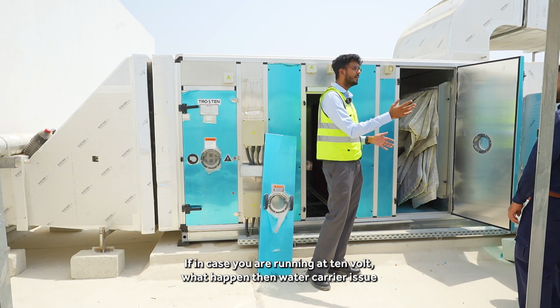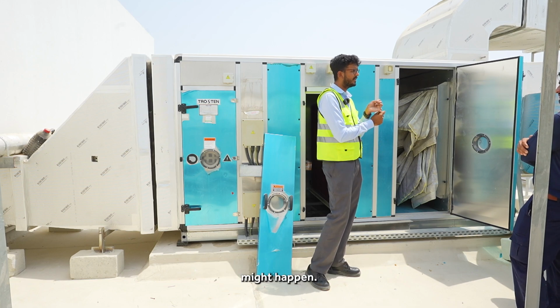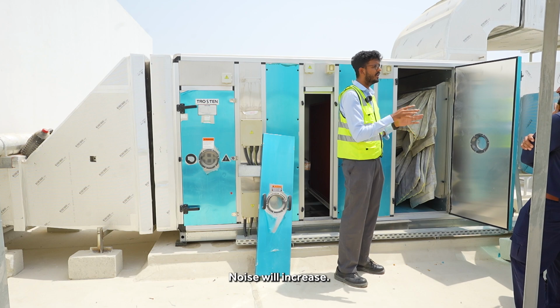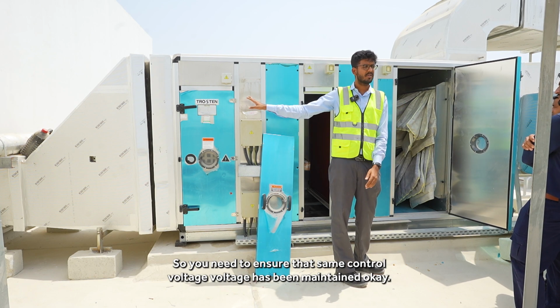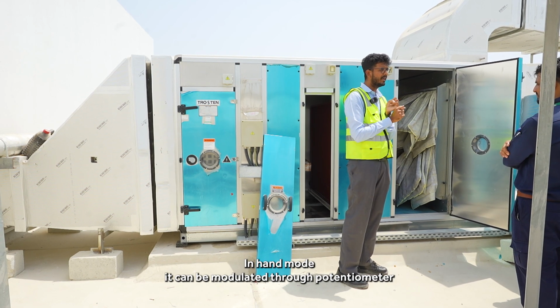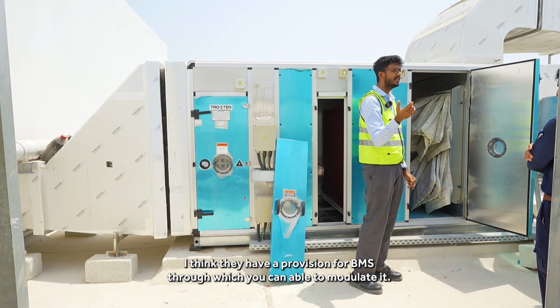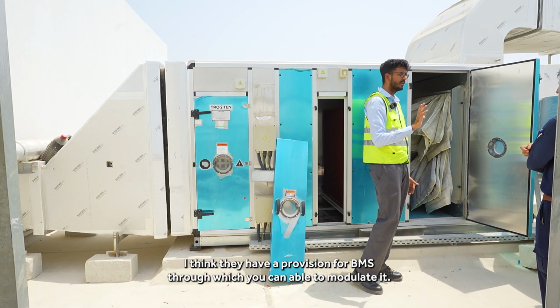If in case you are running at 10 volt, what happens? Then a water carryover issue might happen. Airflow will be more, so water carryover, airflow and noise will increase. So you need to ensure that the same control voltage is maintained. In hand mode, it can be modulated through the potentiometer, which is in your control panel. In auto mode, I think they have a provision for BMS through which you can modulate it.